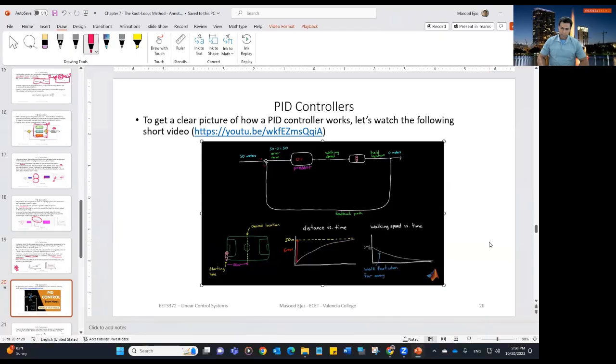With a proportional controller like this, we start reducing the error quickly since we're far away, and then gradually slow down as we get closer and closer to our goal. In this way, we would eventually and asymptotically reach the half field line, at which time the error would be 0, and our proportional controller would multiply that by 0.1, which would generate a walking speed of 0, stopping us right where we want to be.